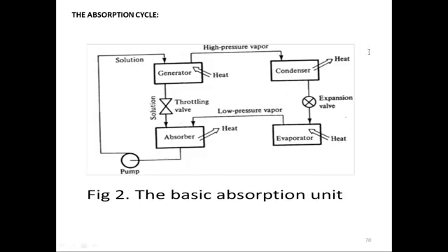If this absorption process were executed adiabatically, the temperature of the solution would rise, and eventually the absorption of the vapor would cease. So if no heat is being released from the absorber, then it will be an adiabatic process. In this case, it will go on for a certain period of time, then this solution will become saturated, and there will be no more cooling process. So for that purpose, the absorber has to reject some heat.